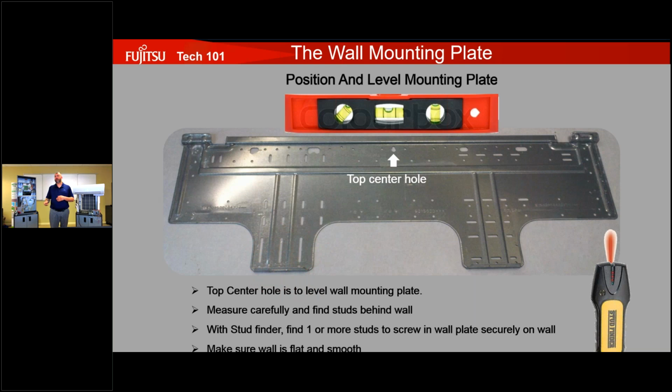When you go to try to unlatch the unit from the bracket, that bracket could end up lifting off the wall and bending, and now trying to get that unit back straight is almost an impossible feat without taking the whole bracket off of the wall. And you're putting yourself in a bad situation there. So if we can get a screw with an anchor in both of these locations, that's going to help you out there.